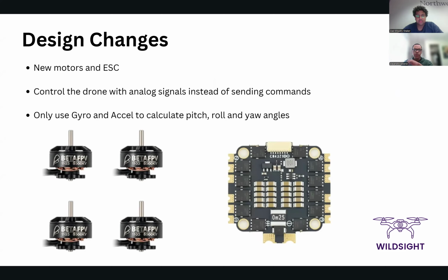And of course, brushless motors can't be driven by just a MOSFET because they have a lot to do with magnets and it's really complicated. So you have to get some kind of special ESC for them. For that, we got a 4-in-1 ESC board, which takes PWM signals from our ESP32 and drives the motors using a bunch of MOSFETs and microcontroller chips, as you can see here.